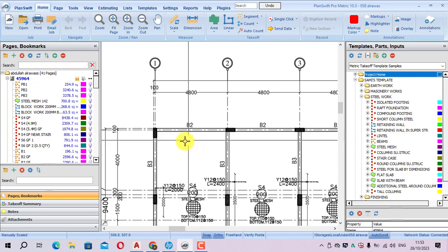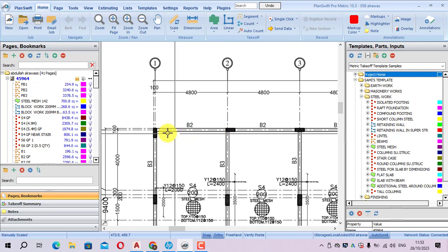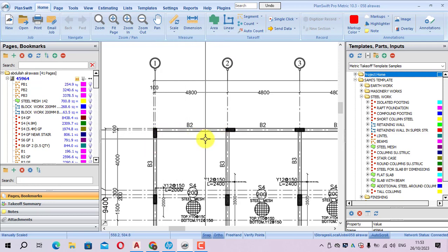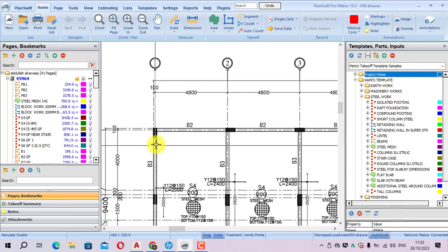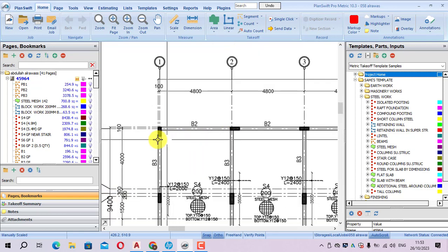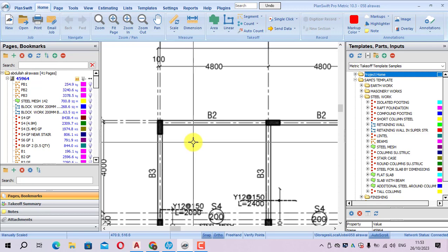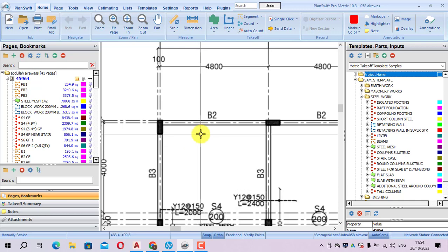Because this template is for steel, there is a breakdown for shuttering and concrete and other things, jacks and other things. So for this reason I will take the slab exactly, not including the beam, because the beam is separate in all of steel and concrete, all of it separate. Here only I will miss some steel from here to here, from here to here, and from here to here. As I mentioned, it will be calculated at the end of the estimation. Then I will put 10%.